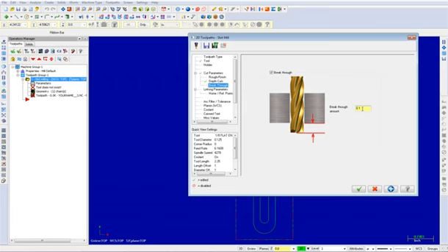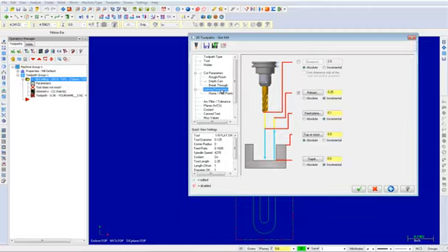You can now choose the linking parameters. Ensure that clearance is enabled with an absolute value of 2. Also, ensure that retract is enabled with an absolute value of 0.25. Next, your feed plane should be an incremental value of 0.1, and your top of stock should be an absolute value of 0. Finally, ensure that the depth is an absolute value of negative 0.125.